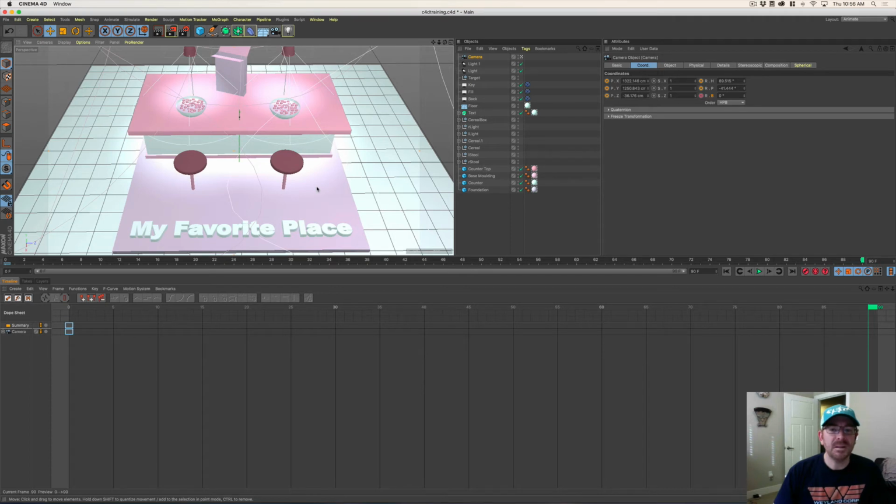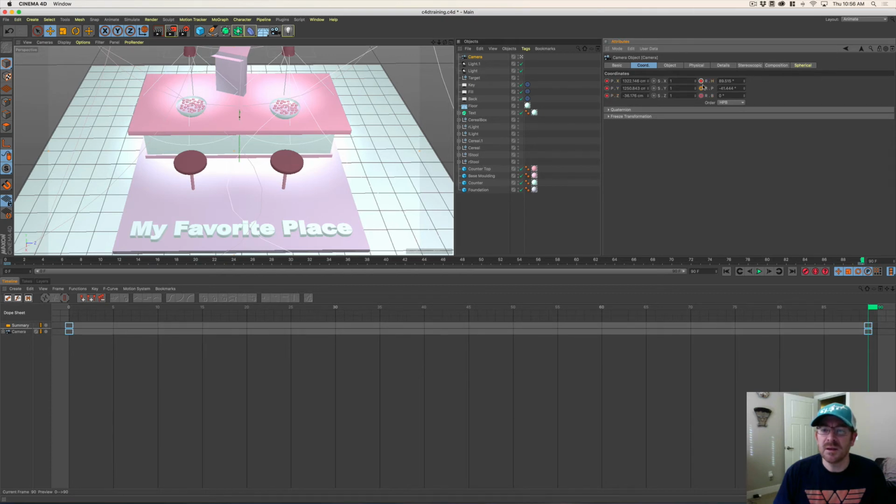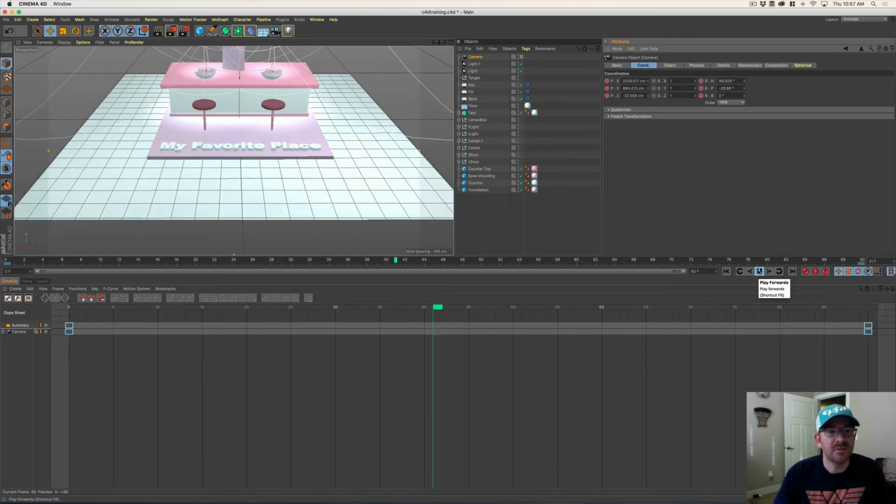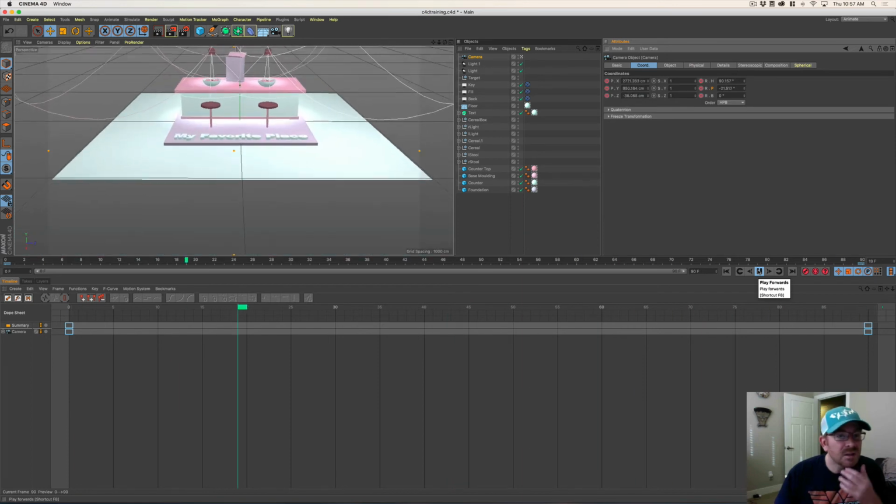All right. The next thing you have to do is lock those keyframes in. You'll notice that those dots have become amber, and maybe one of them is red because we didn't change the rotation. So you've got to click them again and make them red. Red keyframes, or red dots, mean keyframes. Yellow dots mean, hey, there was a change made, but you need to click this dot to make sure it's a keyframe. If you were to drag your playhead somewhere else, it would just wipe them out. So make sure you click those. And now if you press play, you should have an animation. And it should loop for you.